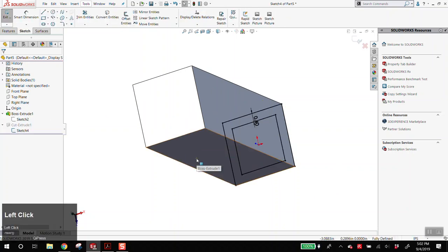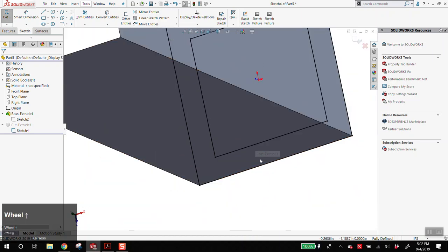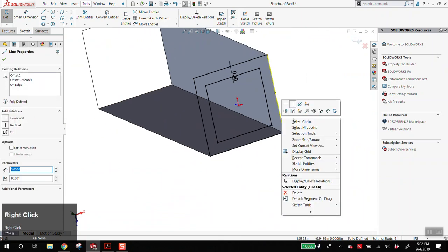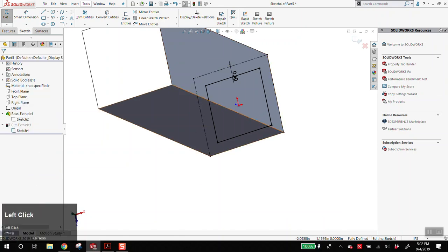And again, just remember when I drew that crazy shape and we made that extrusion. Here now, this is the shape, this is the closed entity now. It's this. So that's why we want to select, again, right click, select chain. It'll select everything on the outside. For construction, we only want to cut the middle, the inside.